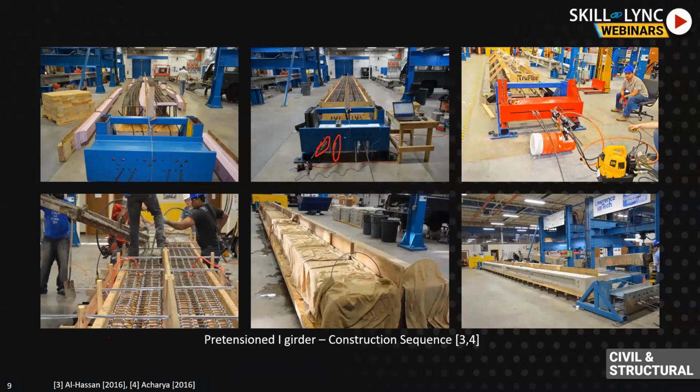While these strands are being pulled, we pour the concrete, and then after a couple of days we let it cure. We put burlap to minimize the heat of hydration, and the strands are still being pulled. When we think the concrete has reached enough strength, we break those strands.